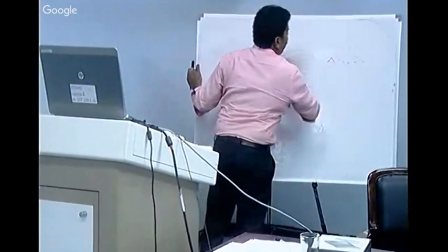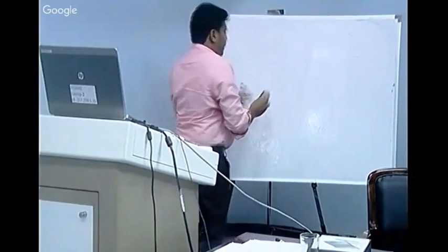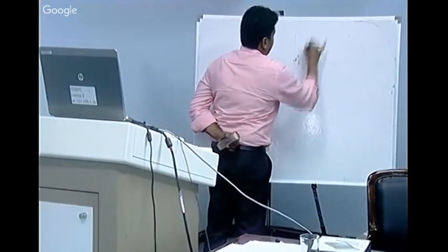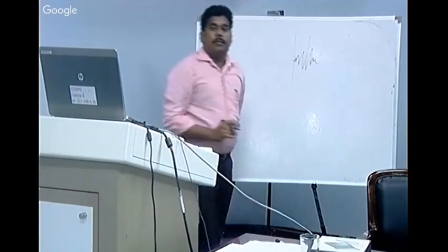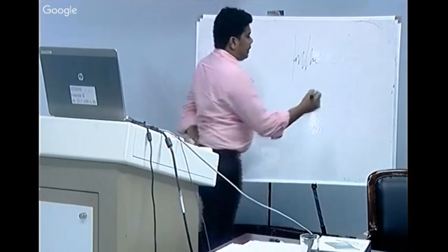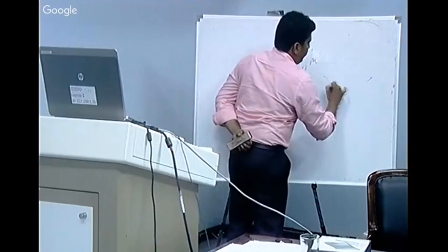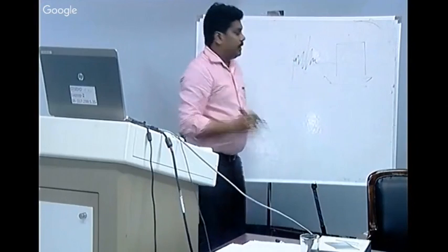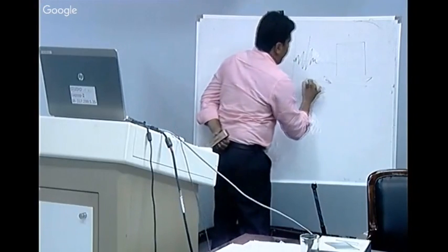Next one is dynamic. We can't use dynamic for a beam. For dynamic, you have to use this kind of loading. When you vibrate the platform, which is supporting any structure, it is called a shake table, and we have a constructed model like this. This shake table will be connected with some actuators.